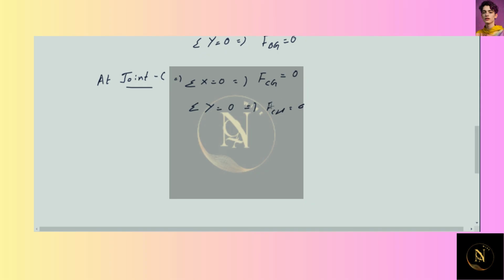Joints having two collinear members, a third member will be a zero force member if no external components act on this member. So FBF, FBG, FCG, FCH, and in the first truss FBC, FIJ, FJK, and FIH are zero force members.